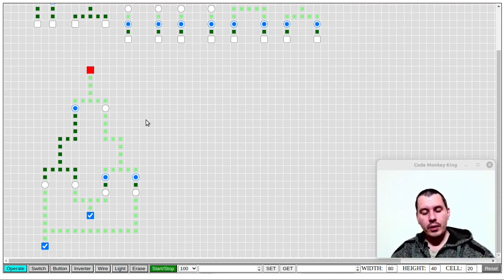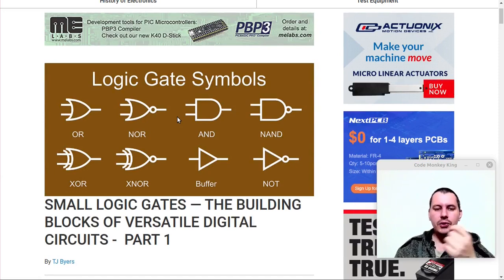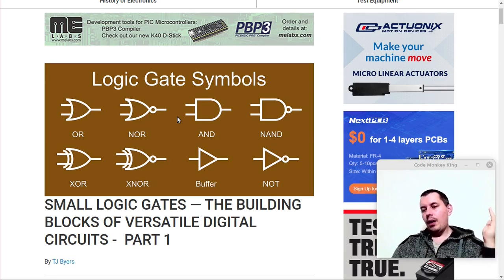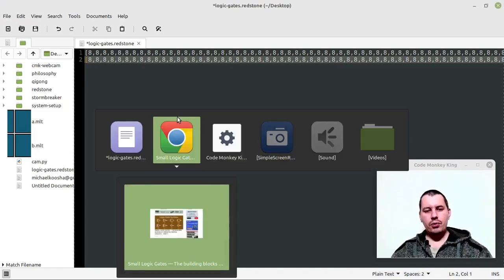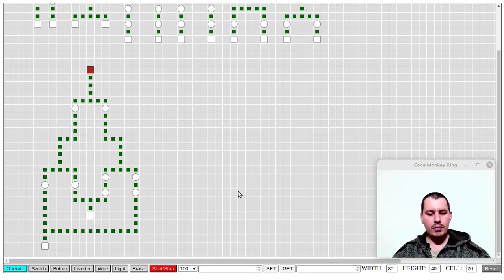And using only these simple logic gates, we can start building way more complicated systems like latches, flip-flops, 1-bit or 8-bit memory registers, and with the combination of the clock that has already been demonstrated in the previous video. But I can very quickly give you an idea how the clock is supposed to be working. For instance, if I just do 3 inverters like this, and if I connect those,